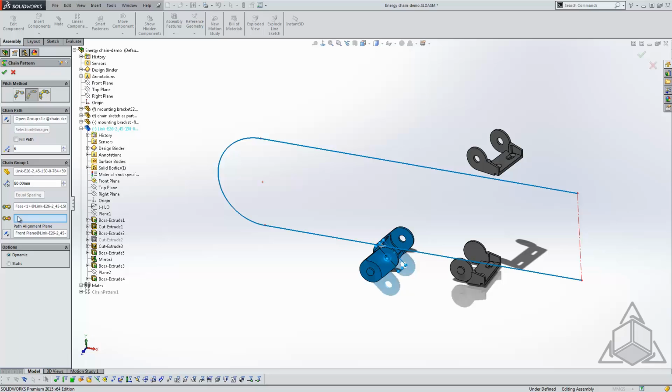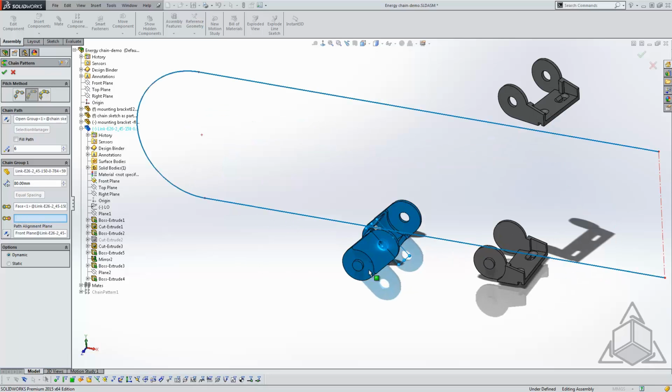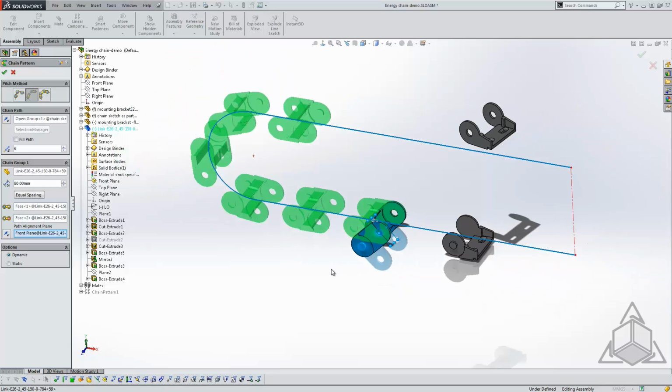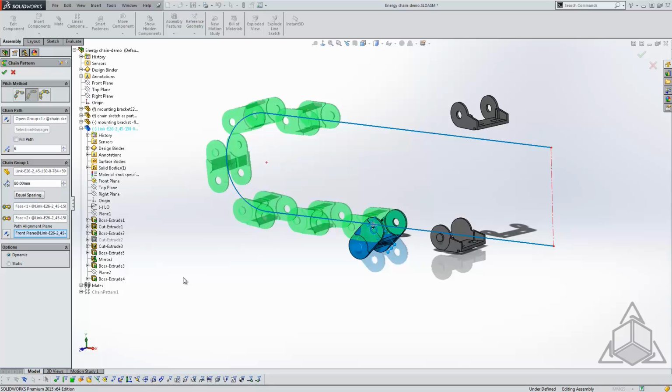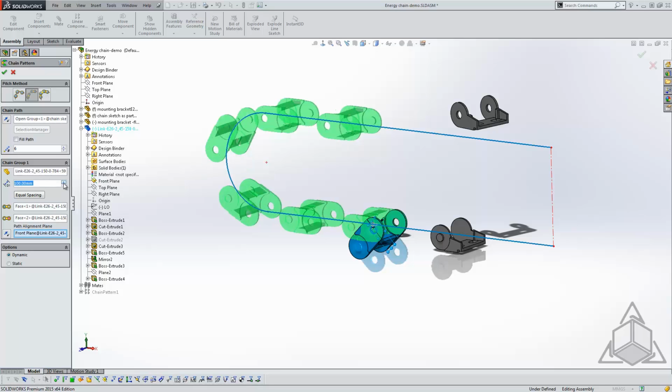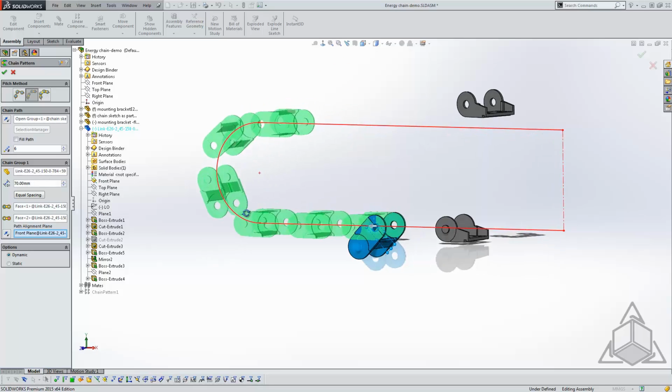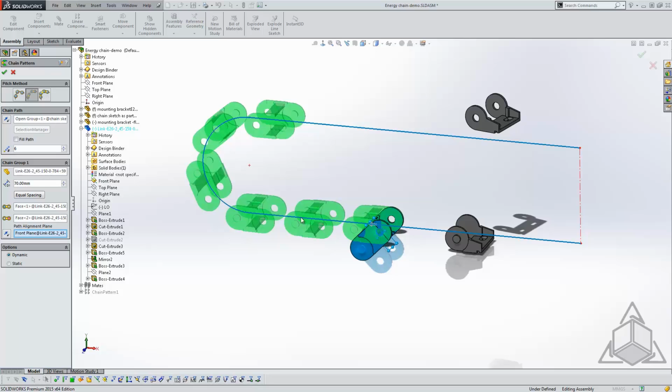So we'll come back and add this here, just using my G key to get in there quickly and back out for the magnifying glass. Magnifying glass, by the way, has been added to the in context menu, so you have quick access to it there as well for 2015. I've left my spacing at 80 millimeters. All right, but we can choose our spacing and we can see that the preview updates accordingly, so it's not based on the length of the component or anything like that. We're just giving it, here's how far apart those components are.